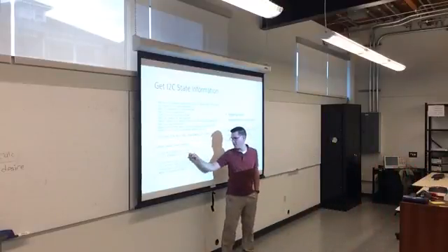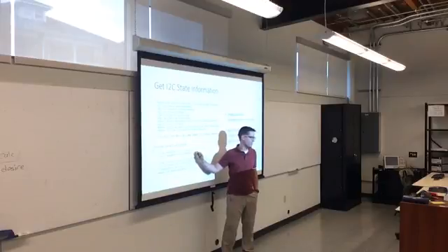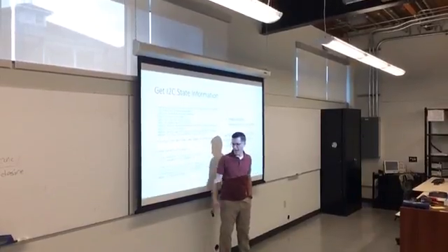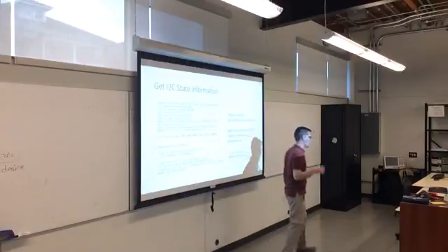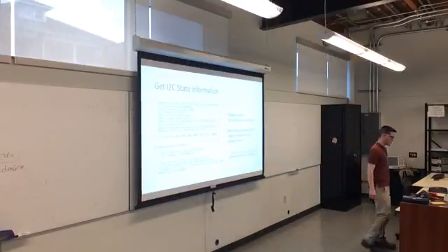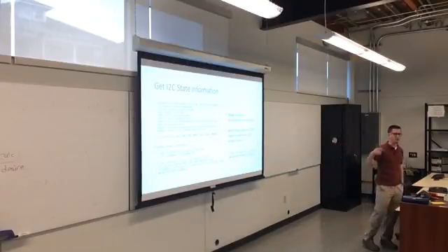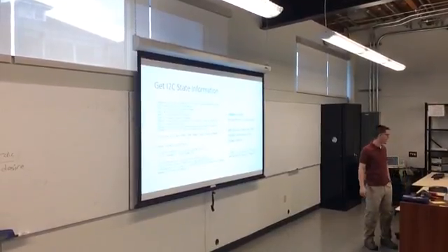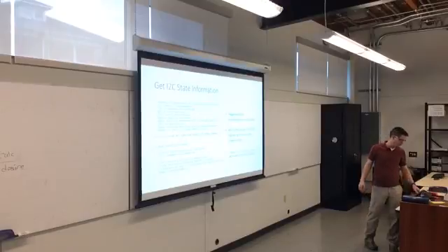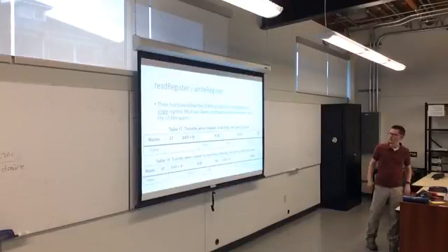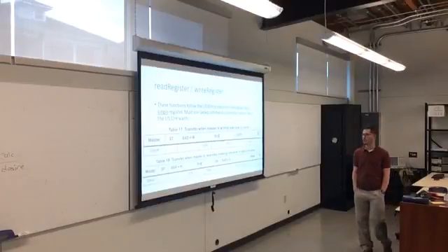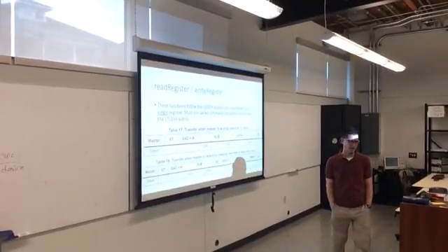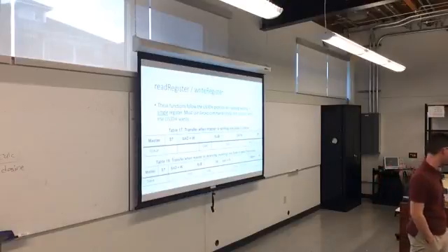There are also other functions in there that will return if something is an ACK, or if data is ready. And those are just reading bits and returning them. Here's what you need to do. You need to implement a function called read register and a function called write register. Read register is used by the accelerometer class to read a particular register on that device.